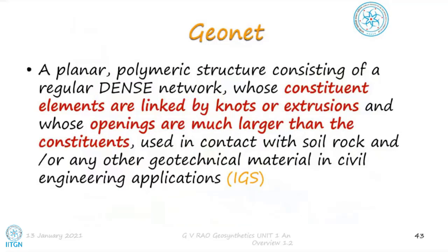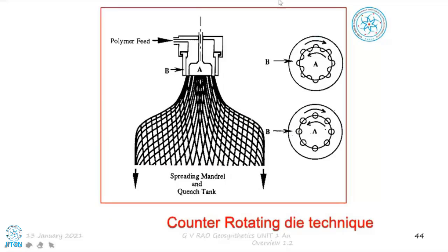We'll come back to the definition again, but let us quickly see. What is it we're trying to do? We have the same polymer feed, maybe polypropylene, PP. And then we have an extruder here, the same kind of extruder. Earlier, the extruder was like making bhujia or sev. That means a number of holes, apertures, through which the polymer is pushed in molten form by screw technology. Now, in this case of making a mesh, a net basically, what is happening?